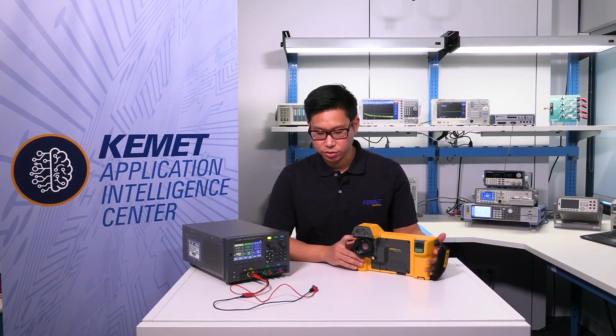Yep, it's always important to make sure. This will give you a good idea of how much your temperature will rise for the application that you're using these inductors for. So you could design around it, and basically, I would design under it. Yeah, you always leave a little room for error.